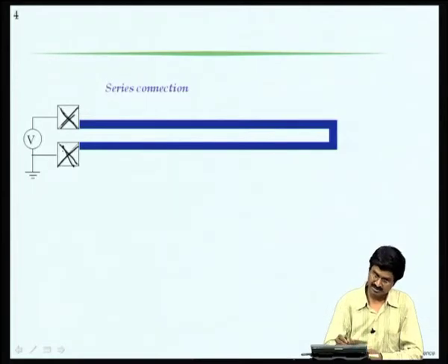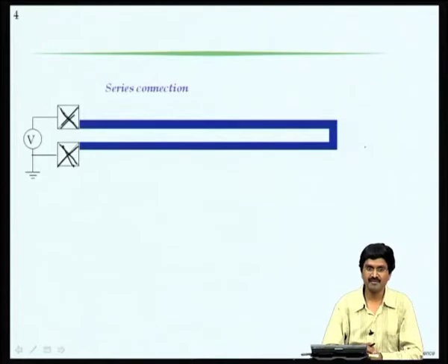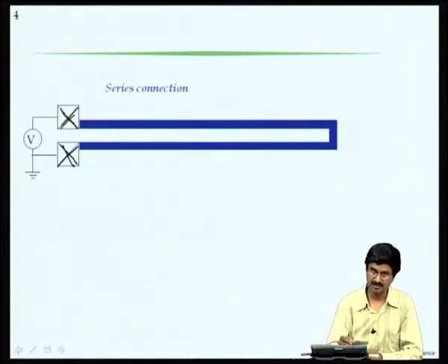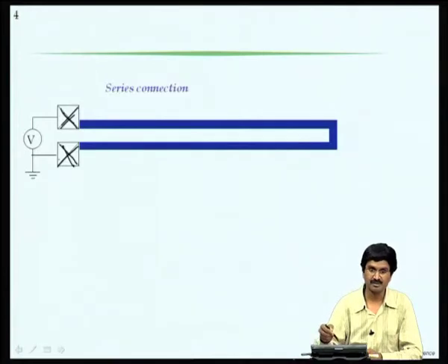One is that the current starts flowing like this. The beam is of uniform width everywhere, so the current density is going to be the same and it is going to flow throughout. There will be ohmic heating, it is going to heat up, and that is not going to be uniform because these are room temperature, whereas heat is generated everywhere. That heat has to go back to the substrate or through convection and radiation to the environment surrounding it, but nevertheless the temperature profile is not going to be constant along this folded beam, but there will be something.